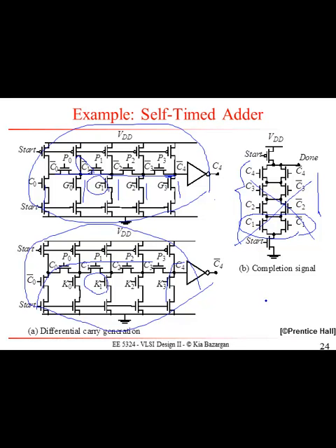But if you are doing all the intermediate signals like what we did with the carry select adder, in which you needed the vectors of intermediate carry signals to combine them with an XOR with the S signals, with the AND signals to get the sum, then in that case you need to AND all of these. So it's all context dependent, and you have to see what inputs are being fed to the registers, and you have to have the done signal for all of those signals that are feeding the pipeline register.